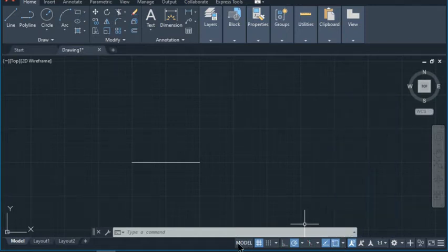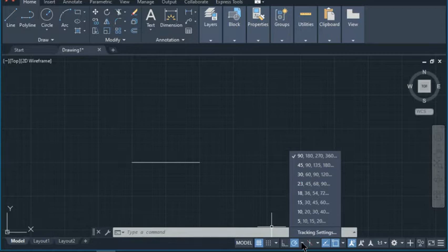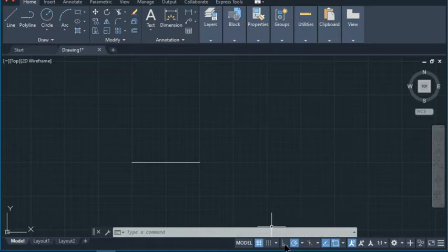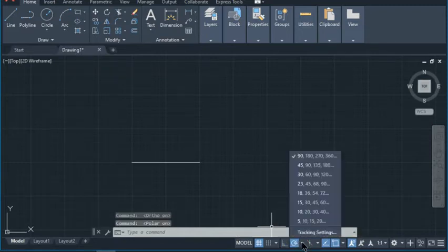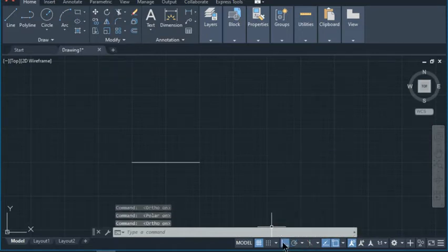That's good. So right down here, this right here is your status bar. Your status bar, you have arrows here, then click it open. This is where you can see your angles when you need them. This right here is something different. Now notice if you turn on the polar tracking, where it shows the angles, then the auto is going to turn off. And if you turn on the auto, the polar turns off. So those two can only have one turned on at a time. Now over here we have all the snaps, right? This snap tracking, you turn on, turn off, right?